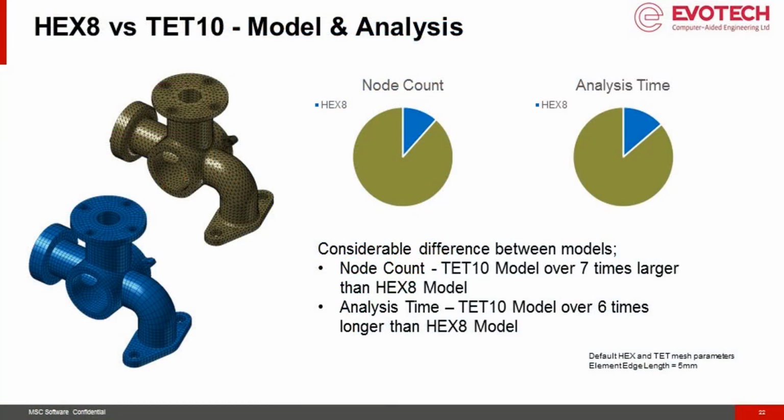So very quickly, one of the reasons why we spend time chopping up geometry to make it hex meshable is that there's a huge decrease in node count for a given structure, and we can see in this simple example that with those changes made to the hex mesh, we can have a much smaller model, but very clear distinction in terms of how the structure is going to work.